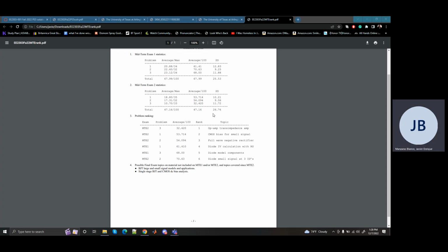What do you do to get that expression? The partial derivative. Right, which in even simpler terms means transconductance. That's more complicated. Simpler terms, what's a derivative? The slope at that point. So G sub D is the slope at your operating point. It's the linear term of it.